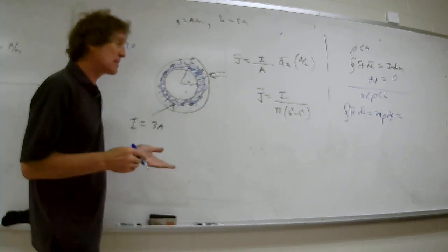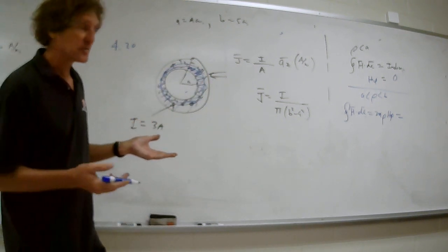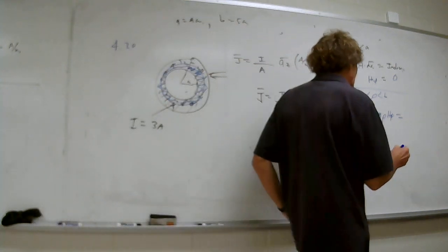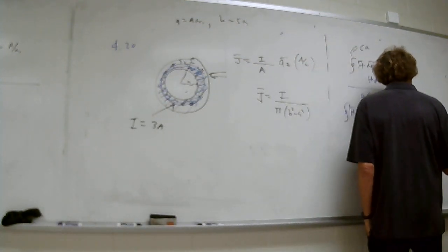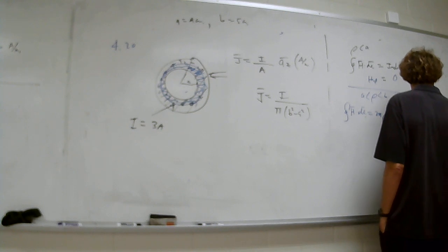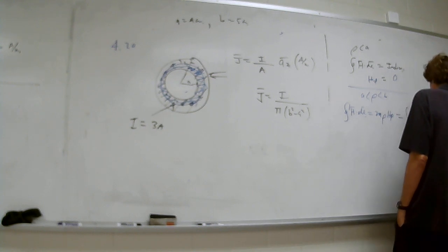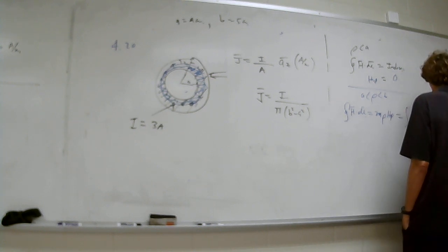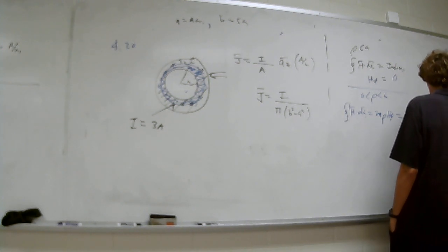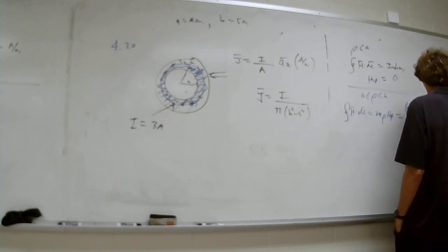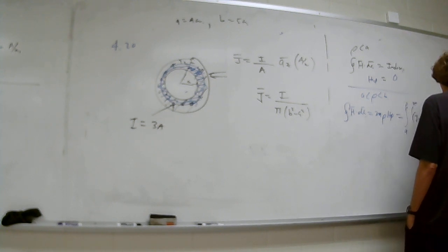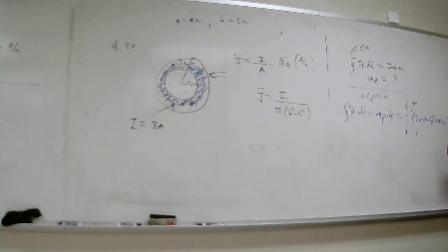If I take the area times the current density, it's not even an estimate, it's exact. Technically, I take a double integral of J, since it's a constant, times the differential surface vector, which is rho d phi d rho. Here, phi goes from 0 to 2 pi, and rho goes from A to rho. You all follow me on this, class?